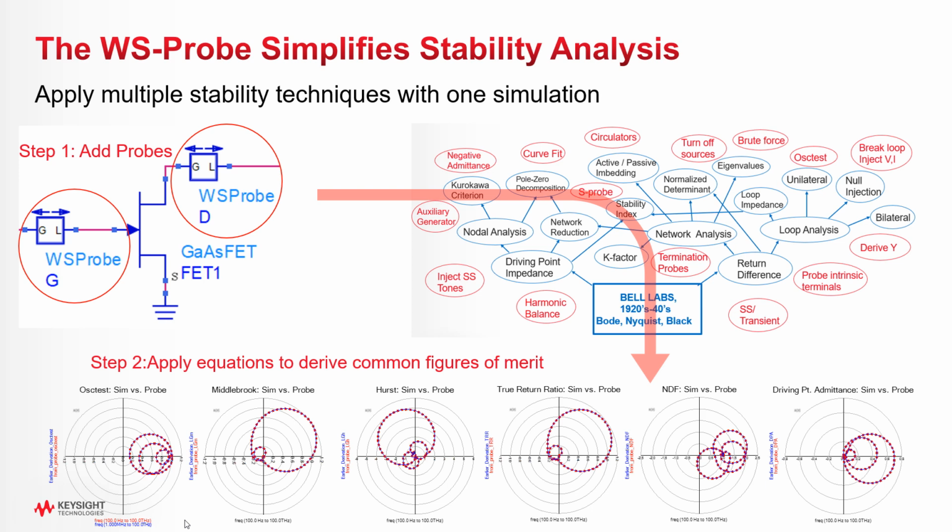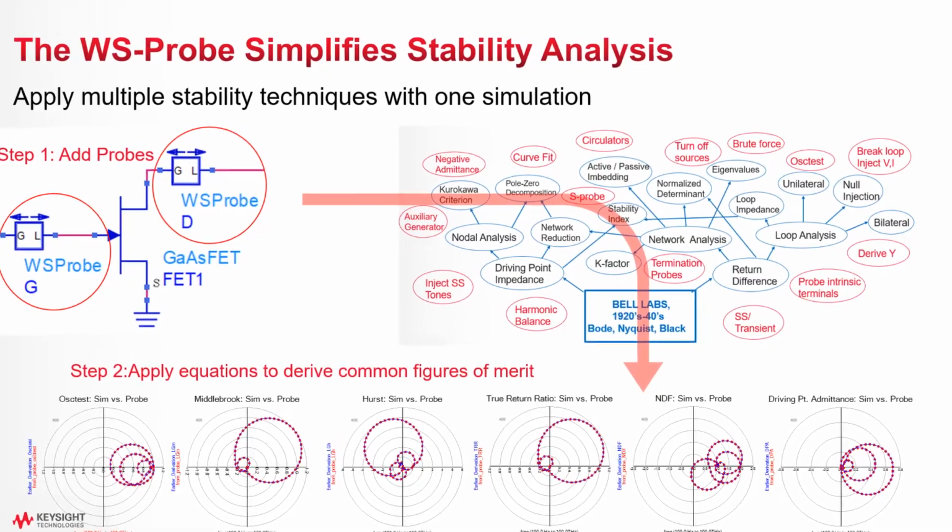The Winslow probe is a general stability probe in the simulation tool. This probe can allow you to apply just about any type of stability analysis technique to your circuit in a very straightforward manner. This probe is nicknamed the Winslow probe because it was developed by Tom Winslow from MACOM. Tom has developed this probe and worked with Keysight to get it into our tools.